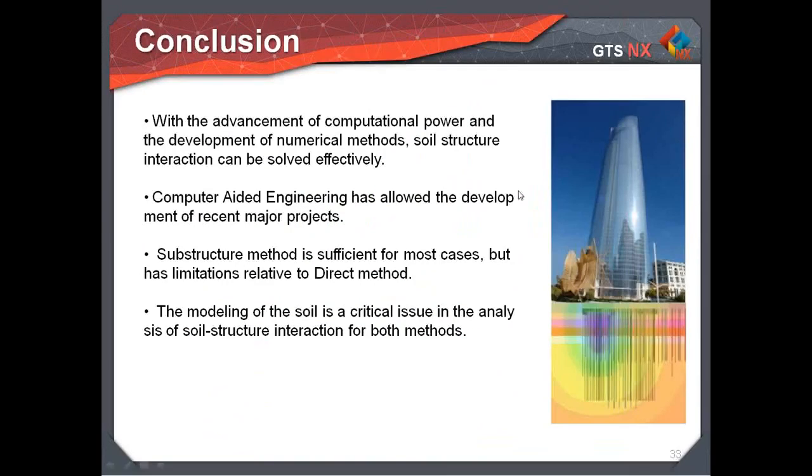And so in conclusion, thanks to these advancements in numerical analysis, we've now seen the rapid rise of these superstructures, particularly in places that we probably wouldn't have seen before, with difficult ground conditions. We're seeing a lot of this development, let's say in the Middle East, where we have superstructures in soft or sandy grounds. It's all due to these new kinds of numerical analysis that allow users to really get a good idea of how their raft and piles are going to behave with the ground through the direct method. For more complicated ground conditions, which is the most important part of your project, you probably want to use the geotech software and ideally use the direct method.